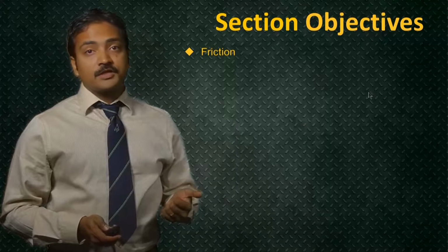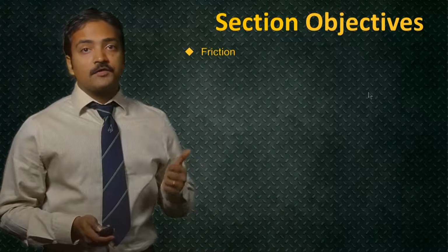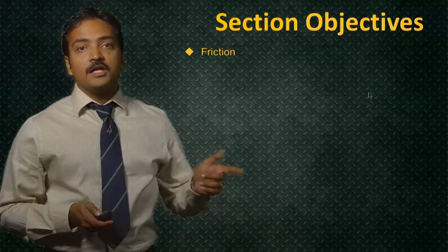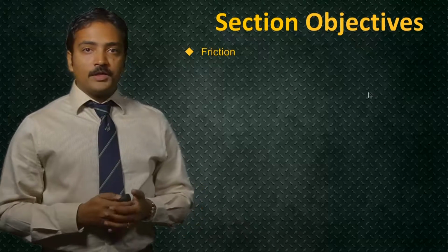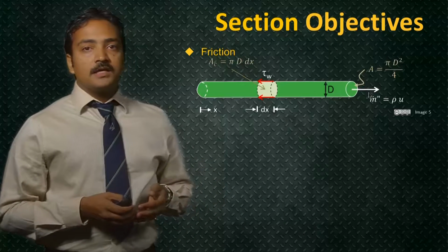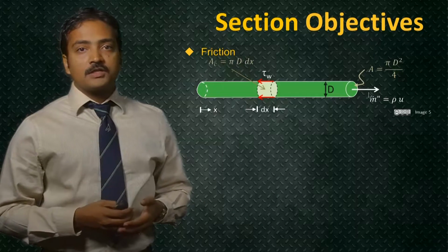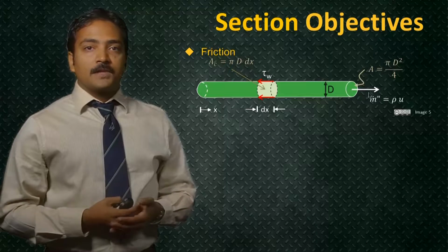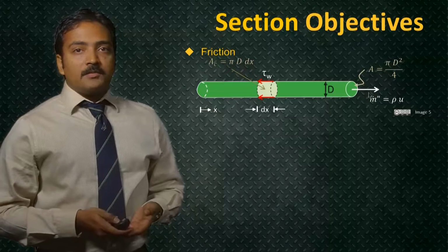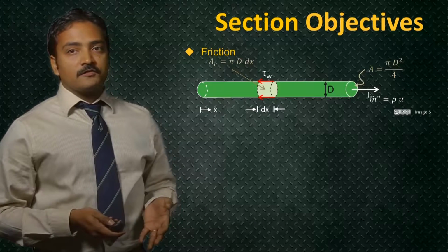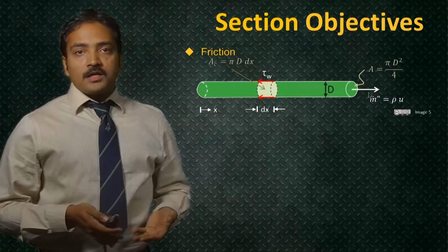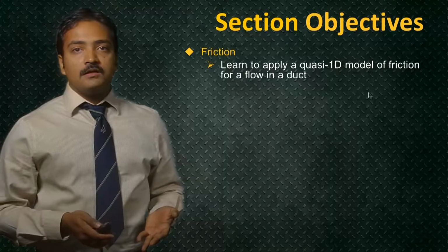First, understand the influence of friction. As we know from many day-to-day experiences, friction exists all around us. For example, anytime you drive a car, the vehicles are going to grip the road and move the car forward only because of friction. Similarly, when we apply a brake, we do so by applying friction on the wheels. In the context of the combustor, when we think of flow within a straight duct, we can see that the pressure is very high due to the inlet compression and the cross-section area is smaller compared to the inlet. In other words, the gas wall contact surface area is high relative to the volume compared to other parts of the engine. Therefore, the flow experiences the effect of friction all along the contact surface where the fluid or the gas touches the wall.